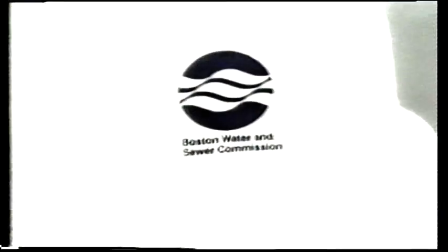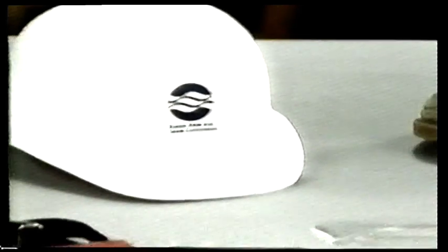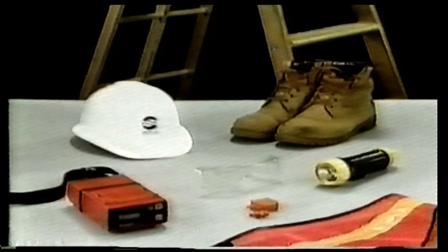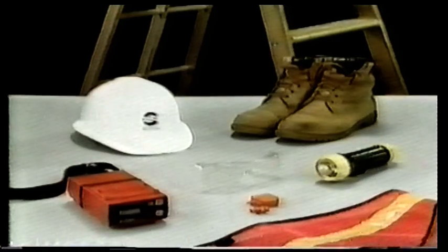Remember that the survey team is not limited to these inquiries. In the course of the interview, other pertinent issues may arise requiring additional questions. The interviewer, by thorough, in-depth questioning, largely determines the overall quality of the survey. When these preliminary questions have been answered, the survey can begin, systematically visiting and inspecting every water usage on every floor in every building of the facility. Again, safety considerations are paramount. The safety checklist should include a hard hat, safety glasses and shoes, earplugs for high noise areas, a battery-powered flashlight, not an electrical trouble light, oxygen sensing equipment for pits, and a wooden or fiberglass ladder.